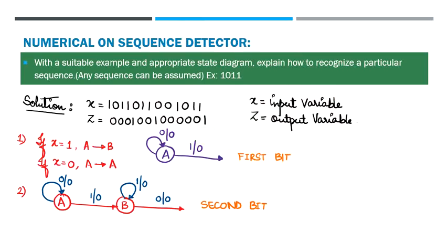So if you observe, the correct sequence in my case, from what I have considered as an example, is present in the input variable 1, 0, 1, 1 here, and once that sequence is detected, z will be equal to 1, and then again I have another correct sequence here and z will be asserted. So 1, 0, 1, 1, again z will be asserted. So you can see that there's a repetition and you can see the number of times z is being asserted.